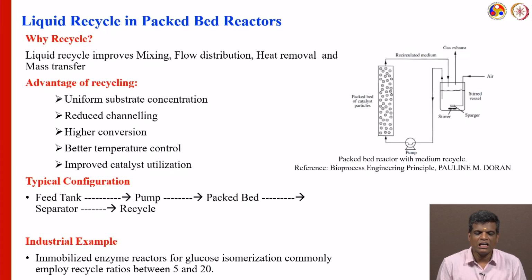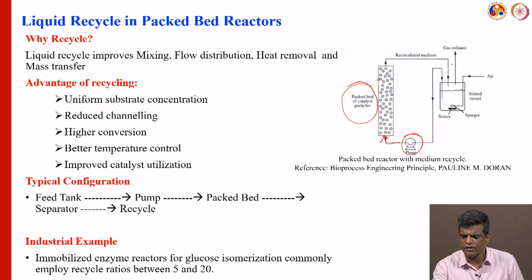So, first, what is the liquid recycle in packed bed reactors? Here you can see catalyst particles loaded in the packed bed column, and there is a pump. You always pump the liquid, and the medium is recirculated here. There is a stirrer, then a sparger, and the air we are passing here, and of course the gas exhaust. So, why do you want to recycle?